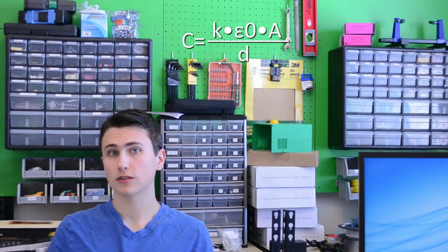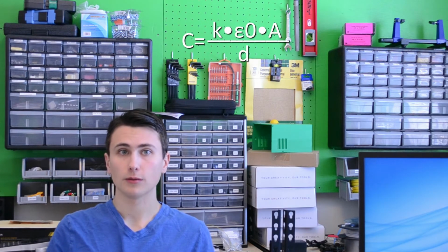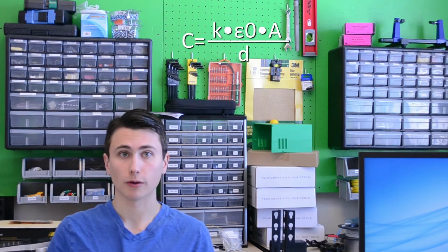The basic concept behind a capacitor is that if you have two metal plates and you bring them close together without allowing them to touch, a charge can accumulate on the metal plates. This charge induces electric fields that store energy within a capacitor. Now this is dead simple, in theory. You can construct one of these using a sheet of glass and a couple sheets of aluminum foil glued to either side. The equation for a parallel plate capacitor is shown on screen. This equation is generally used for general conceptual conversations about how capacitors work.